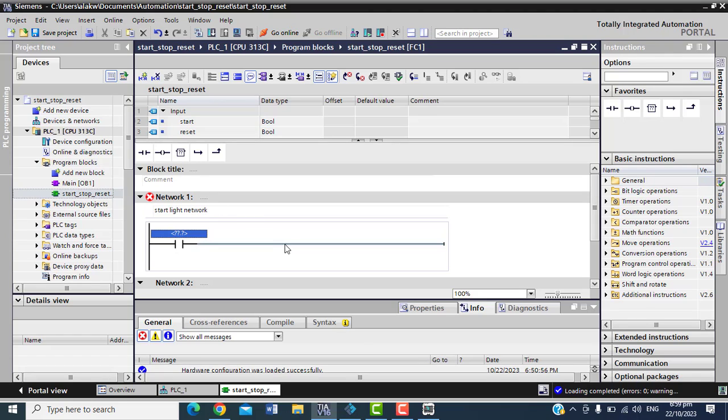You get the point. So if I come here and select this one as output, whenever the signal goes on, power will flow from here to this place. But because I didn't put a normally open contact here, you will see that it cannot flow. It will break the flow to this final output. Whenever this one closes, anytime I press the start button in the field, it will close. And immediately it closes, I expect the signal to pass through and come to this one. And again, I want this one to be the start light.